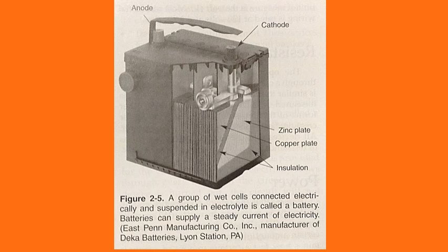Generator. A battery is just one of the ways to generate and drive an electrical current. A second method is with a generator. Driven by some mechanical force, a generator is a device that creates differences in electrical potential between two electrical poles. It moves electrons from one terminal and deposits them into the other terminal. This is accomplished through electromagnetic induction. This process will be explained later as we discuss generators and alternators.